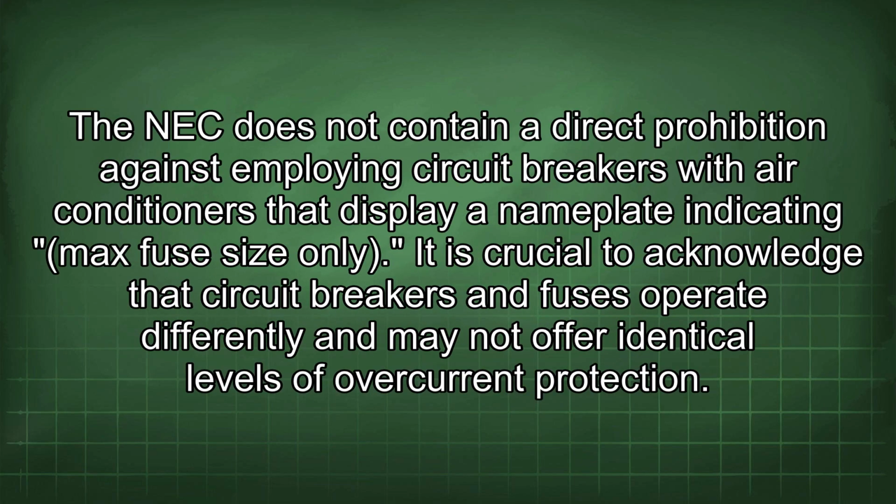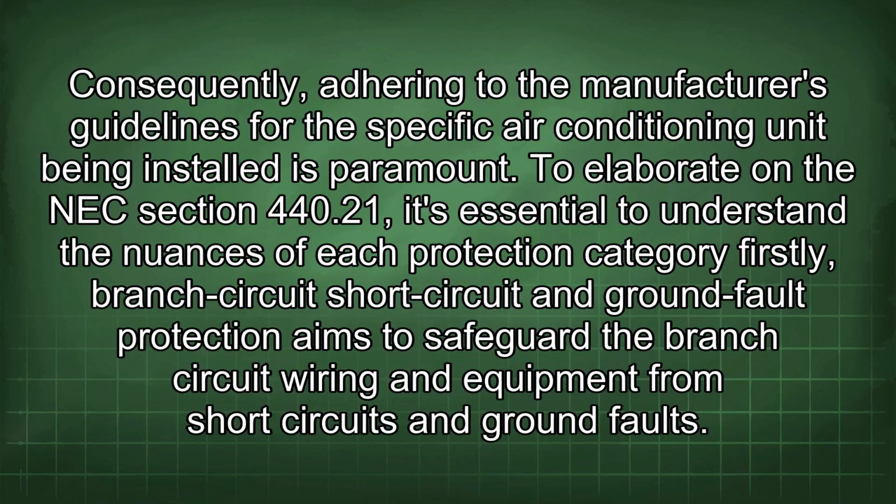The NEC does not contain a direct prohibition against employing circuit breakers with air conditioners that display a nameplate indicating max fuse size only. It is crucial to acknowledge that circuit breakers and fuses operate differently and may not offer identical levels of overcurrent protection. Consequently, adhering to the manufacturer's guidelines for the specific air conditioning unit being installed is paramount.